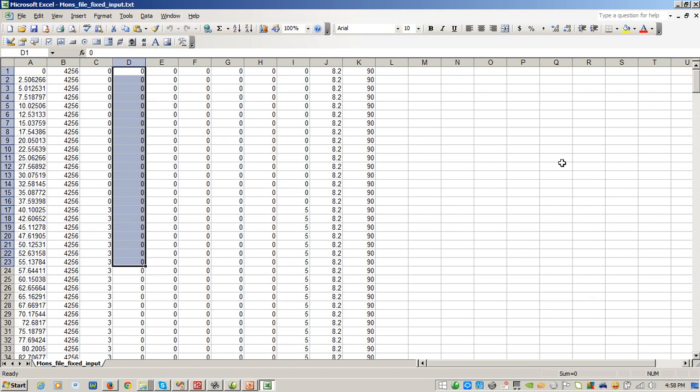So it's more there to represent the data, but the way I worked it out was I figured out the drag, I knew the gear ratio, and from that I deduced the required engine torque. Dividing that by the max engine torque, I determined my throttle ratio. Now, here's the key.